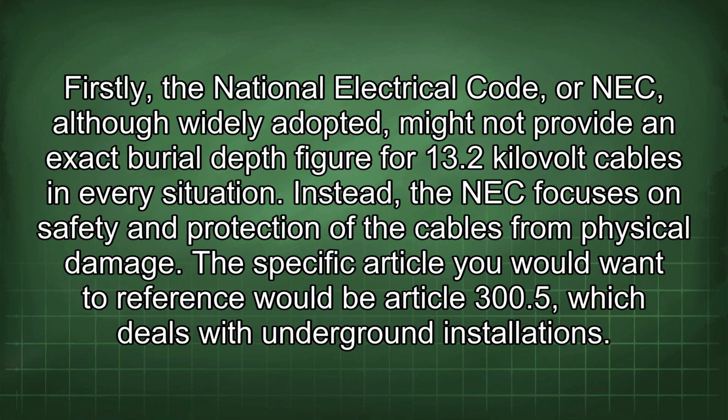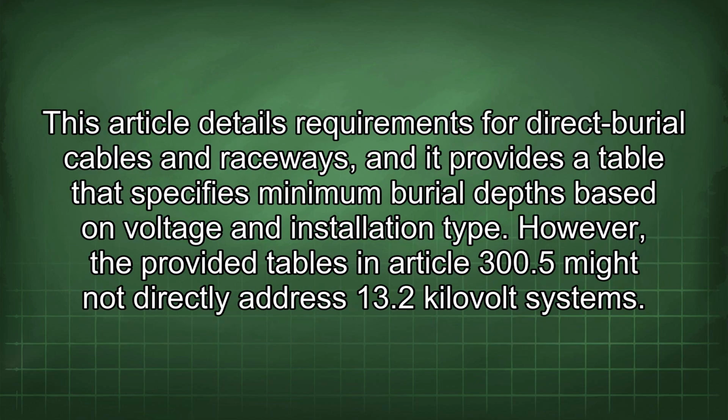Firstly, the National Electrical Code, or NEC, although widely adopted, might not provide an exact burial depth figure for 13.2 kilovolt cables in every situation. Instead, the NEC focuses on safety and protection of the cables from physical damage. The specific article you would want to reference would be Article 300.5, which deals with underground installations. This article details requirements for direct burial cables and raceways, and it provides a table that specifies minimum burial depths based on voltage and installation type.